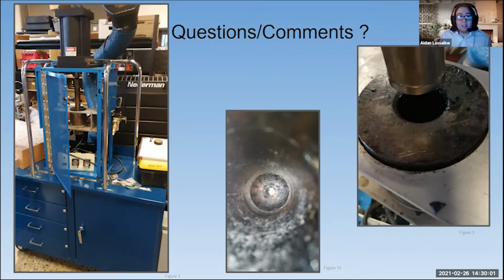So the purpose behind shredding the plastic is what I believe you're asking, rather than using pre-made beads. We want to be able, and currently we're doing this with Tim Hortons lids, to shred them up to about the size of your fingertip, and then they can easily go in there, be melted and pushed through the nozzle. Beads are just too hard to come by pre-prepared, and we want to be able to implement this in landfills.